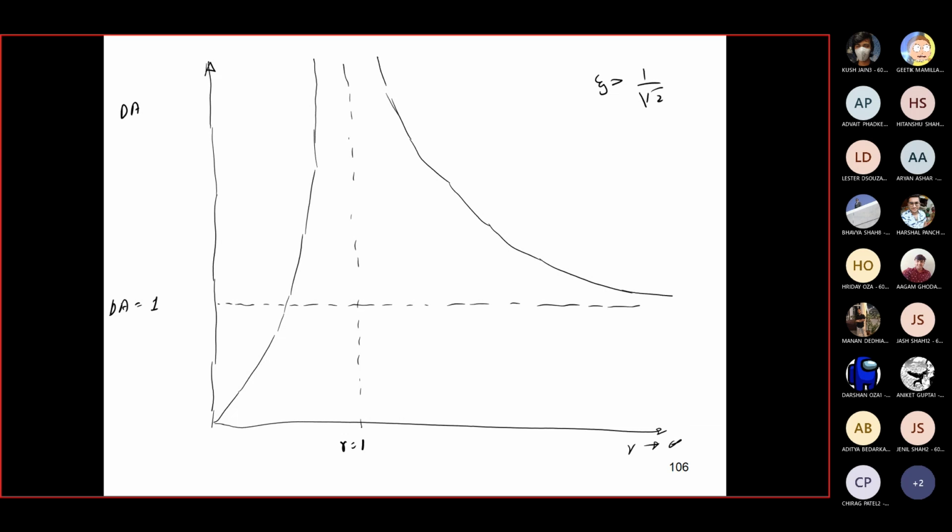All right. So in the earlier case, if you remember the magnification factor curve, how were the peaks shifting? R corresponding to dA max is equal to 1 upon square root of 1 minus 2 zeta square, correct?